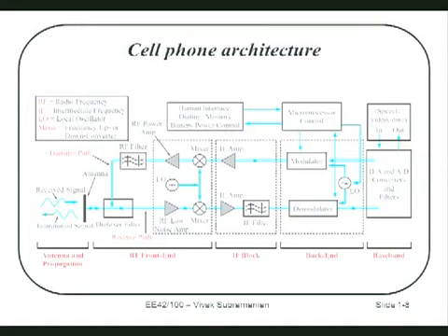That would be an electrostatic interaction where it's responding to the charge. Rather, it responds to the charge that your finger pulls out of the panel when you put your finger on it. So basically, the way the iPhone touchscreens work, there's a series of rows and columns, and on the rows and columns, there's a capacitance between each row and column intersection. When you put your finger on top, you bleed some of the charge out.